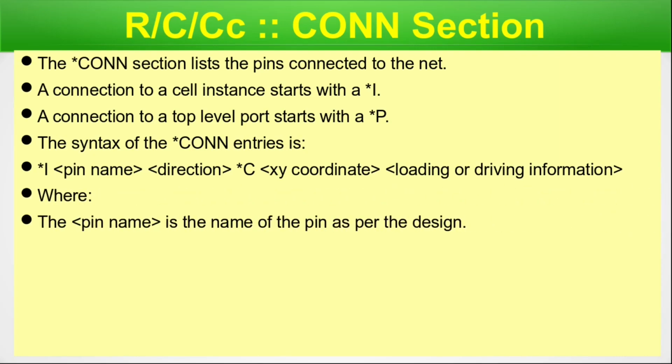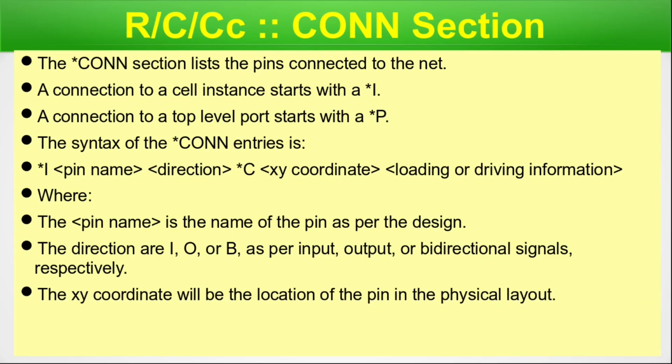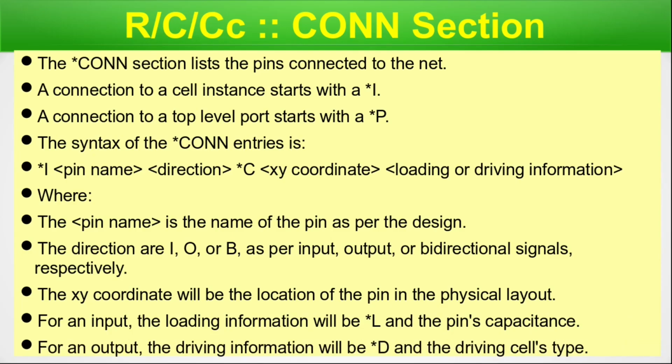The pin name is the name of the pin as per the design. The directions could be I, O or B, for input, output or bidirectional signals respectively. The XY coordinate is the location of the pin in the physical layout. For an input, the loading information will be *L and the pin's capacitance. For an output, the driving information will be *D and then the driving cell's type. So we have a short and sweet description of the CONN section here. Now we are done with this particular slide, so let's move on.